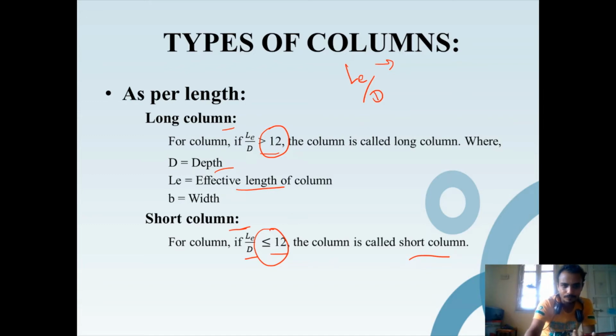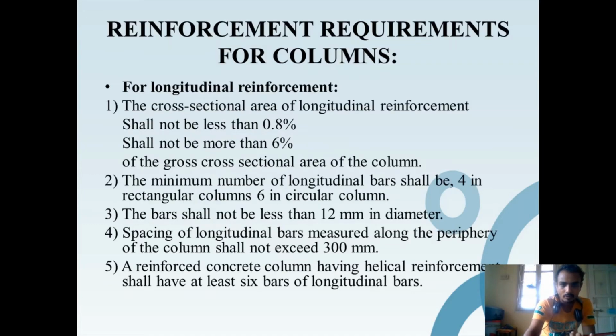Here are some requirements for reinforcement. The longitudinal reinforcement shall not be less than 0.8% or more than 6%. So in between we can provide 0.8% to 6% of steel.